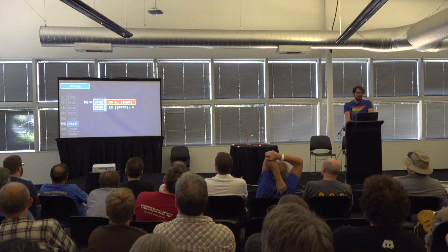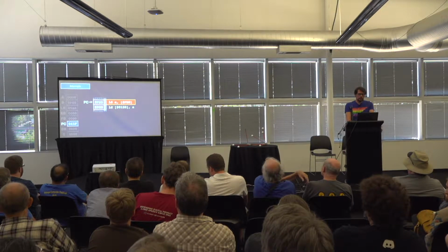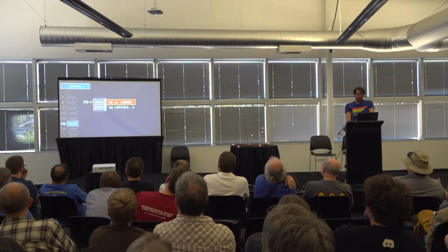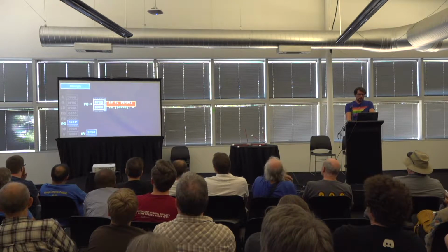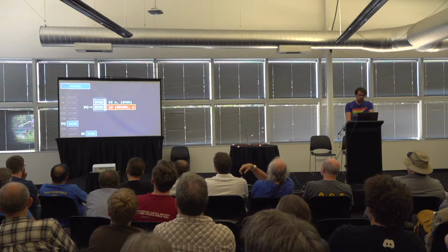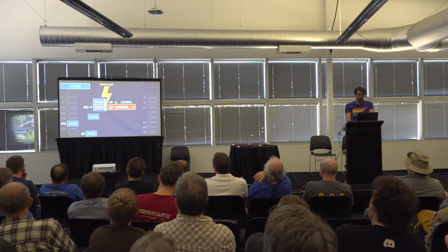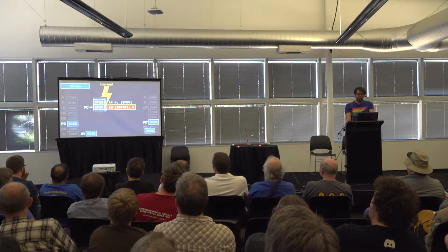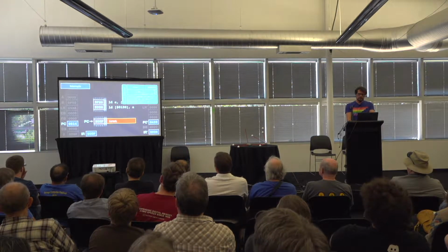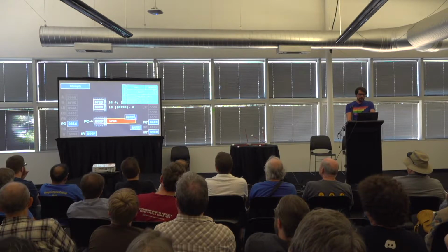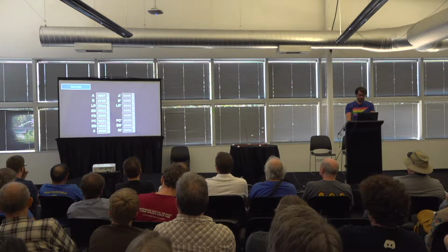When I/O devices need to signal the CPU, they can interrupt normal execution. Next to the program counter, which points to the next instruction, there is the instruction register, which holds the current opcode. When an interrupt happens, the CPU copies PC into a special memory location PC prime and IR into IR prime, and then jumps to a magic location depending on the type of interrupt. In this example, 814.